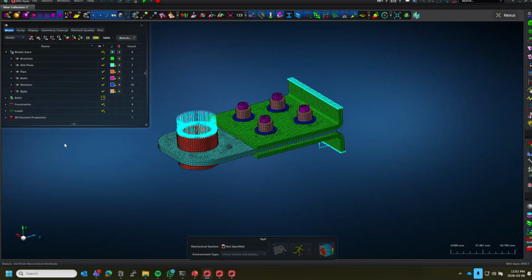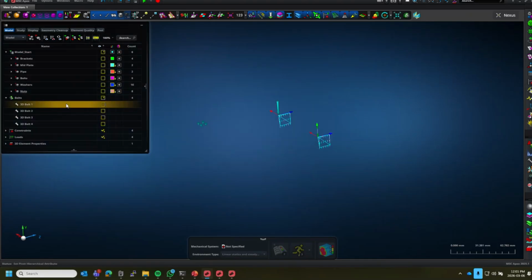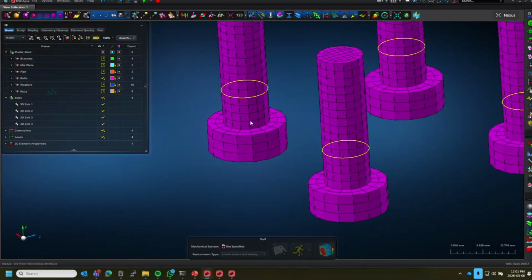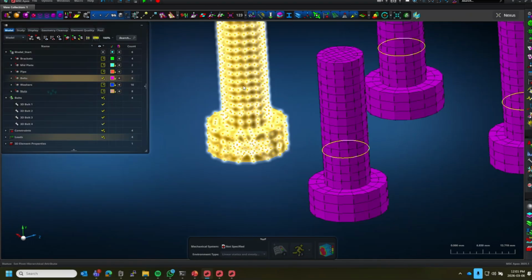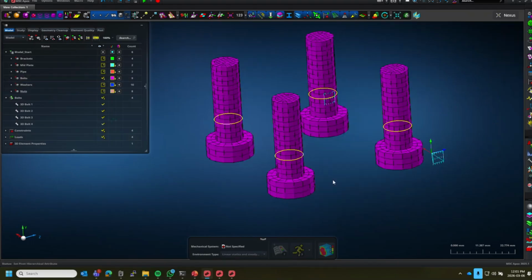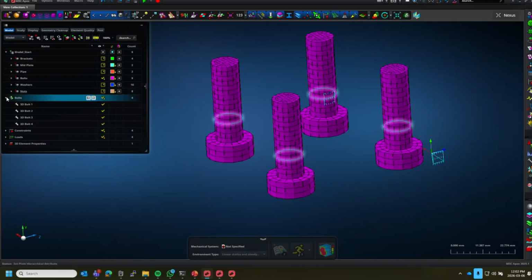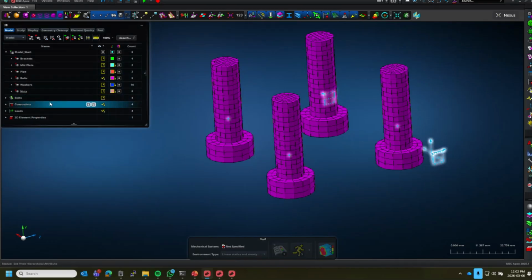In terms of the modeling further, we've got a couple of bolts, and we specifically use a feature called bolts in Nastran. What this does is apply the load, at least initially, and then in the second load case, after we apply the preload, we can lock that in place. Think of the first as tightening the nut until it reaches a certain load, and in the second I then lock the nut in place so that it doesn't turn further. I'm not going to explain this in more detail. We assume you either know it or we can look at that separately.